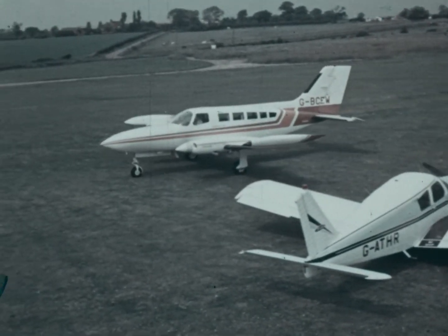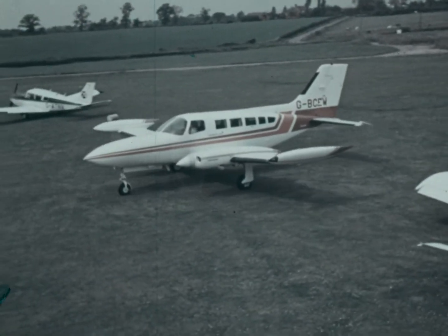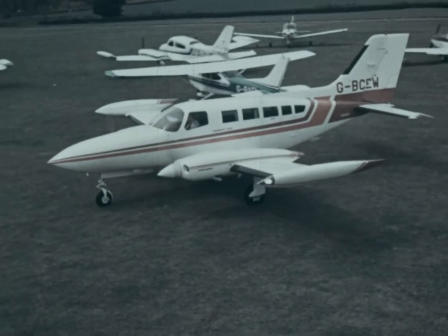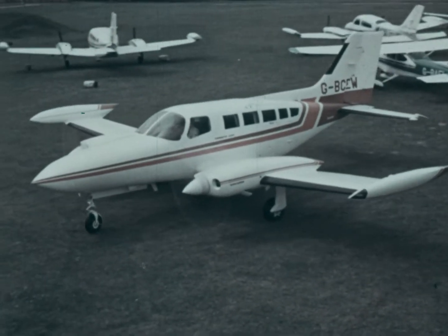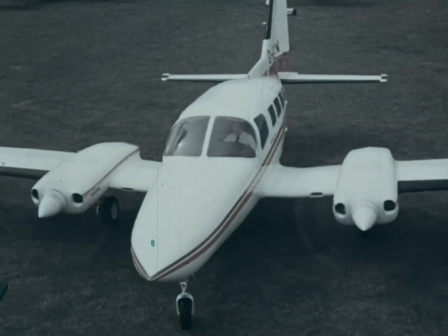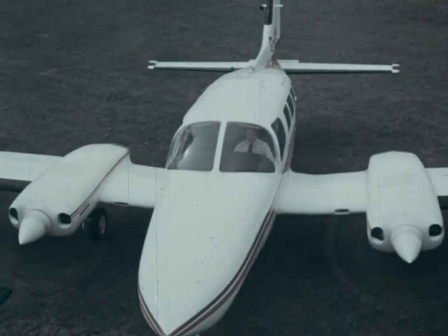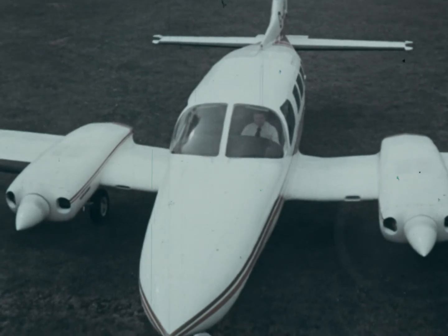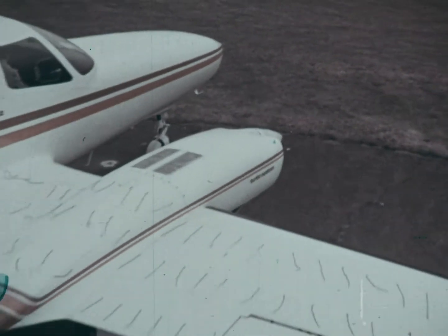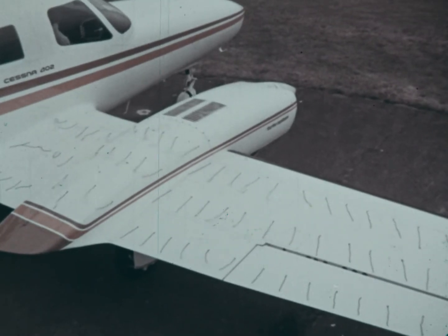The twin-engined airplane differs from the single-engined in several significant ways. The most important aerodynamically is the way in which thrust is usually divided by mounting the engines on the leading edges of the wings, on either side of the fuselage. This has the effect of directing the slipstream of each propeller over the wing itself, thus augmenting lift over a considerable proportion of its span.